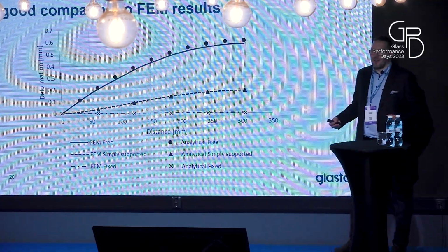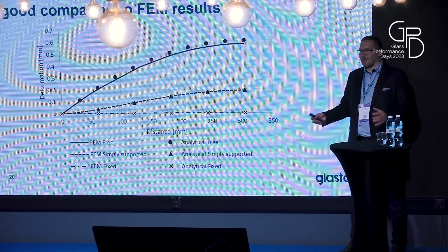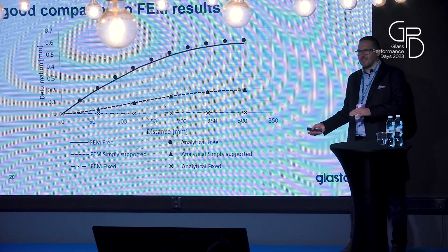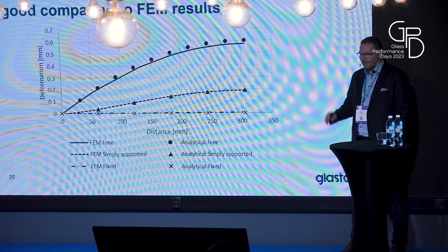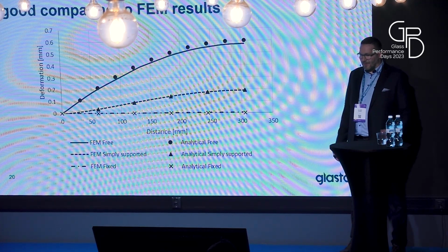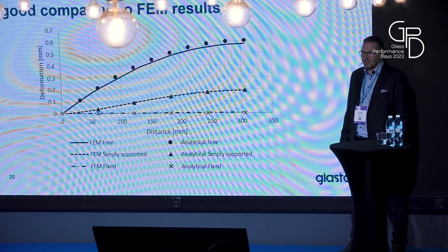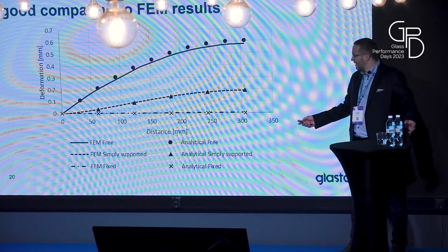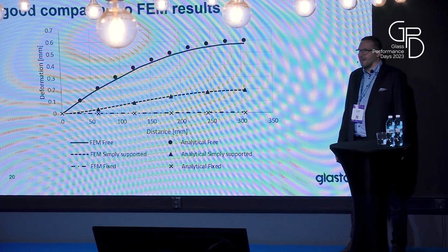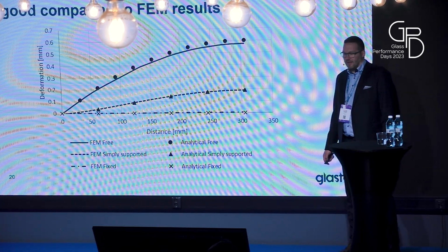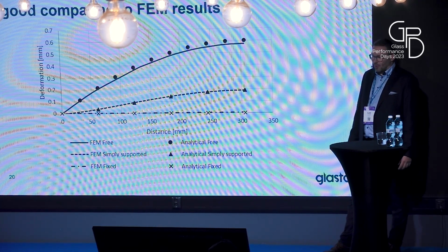So with analytical solutions, you can only get extreme cases, either fully fixed or simply supported. Something in between is difficult for analytical solution, but with finite element it's easier. But in that case also it's difficult to find what's really the right support from the edge or edge constraint.